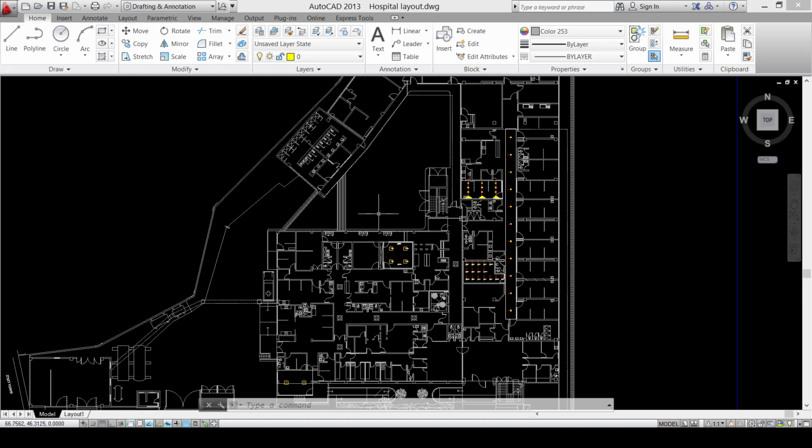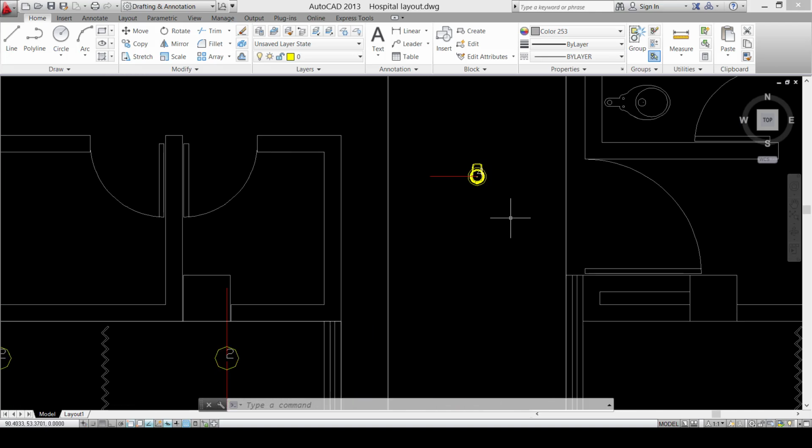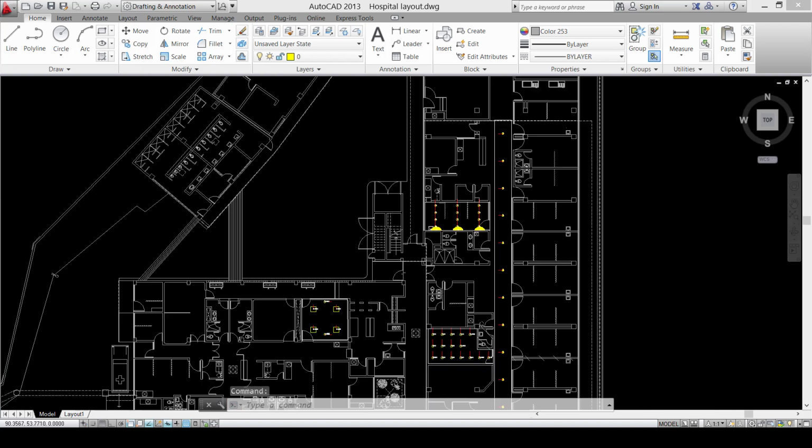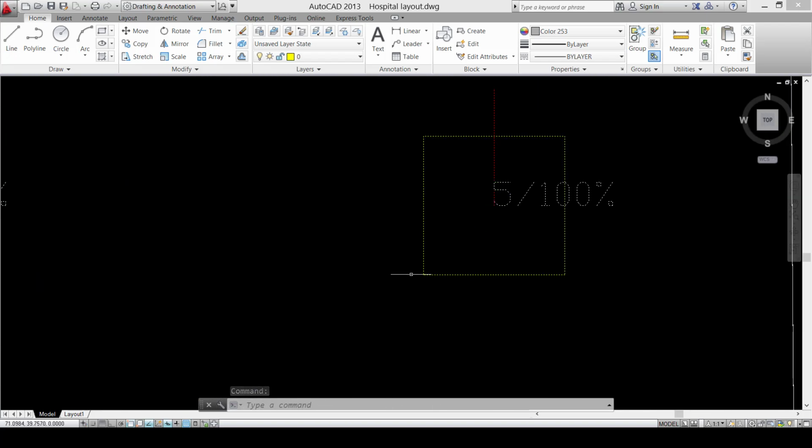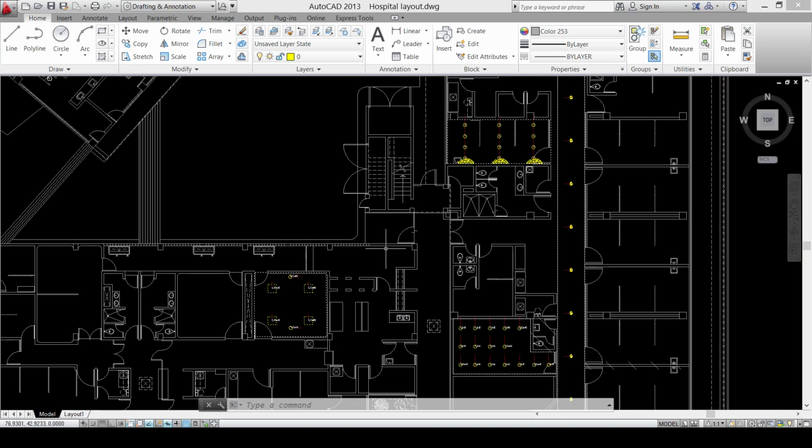Very good. Now after inserting the CAD luminaires, we need to work on the wiring design for those luminaires. But the important note now is that in the real actual design, we don't work on those DIALux samples, or we don't work on those DIALux luminaires. So we will not work on this sample of this spot, for example, or we will not work on this sample of this recessed luminaire. But we work on some other samples for each type of luminaire that are more popular in the actual design, and we add all of those samples, which are the actual samples which we are working on. We add them on a legend or some tables that contain the samples which we need in our actual electrical design in the CAD software.